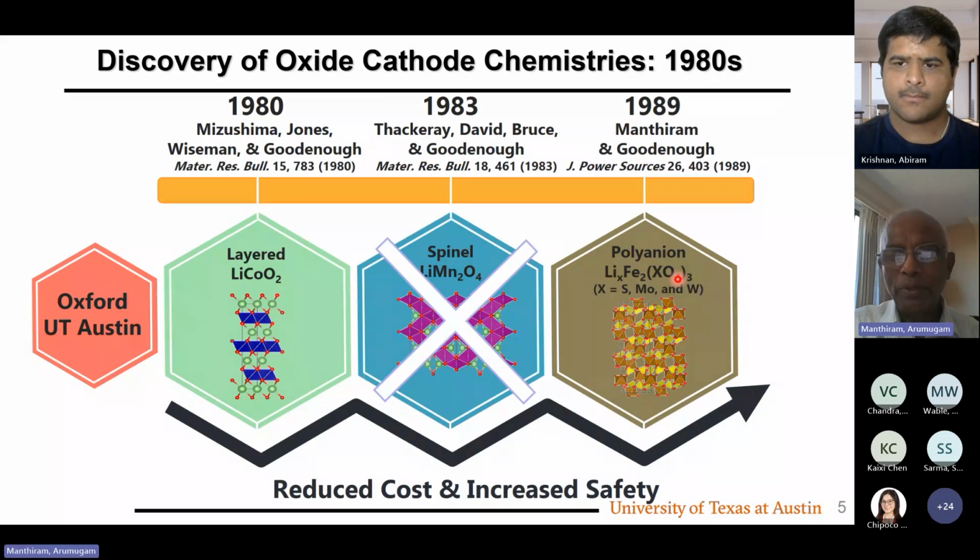Now, we worry a lot about cost and safety. This is more expensive. This is less expensive. Iron containing materials are the least expensive as far as metal oxide based cathodes. Iron is the cheapest. You know, steel. Everywhere you see it, cheapest, one of the most abundant elements. Also, this will release oxygen, more safety issues. Lithium manganese oxide is better.